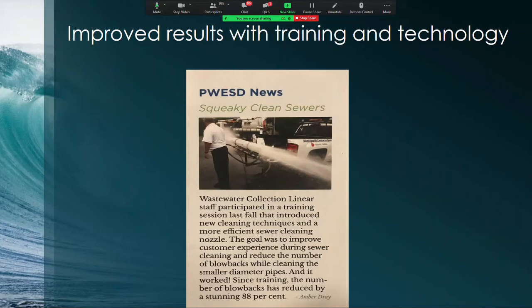And what we ended up doing for the City of Ottawa is we talked to them about changing their methodology, using Tier 3s, reducing the speed, dropping the pressures and flows, and we reduced the incidence of blowing toilets by 88%. They were thrilled. The cost to them was a little over $1,200 to $1,400 a nozzle, and it's just a regular cleaning nozzle, lean and mean on water, and just does a heck of a thing for them.